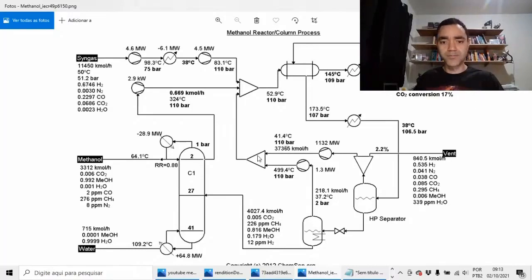And the main purpose of the process flow diagram is to show the heating material balance, or to be the reference for the heating material balance. But this document is also important because in some companies, maybe in most of the companies, depending on the company, it is a reference for building the human machine interface in the control room.